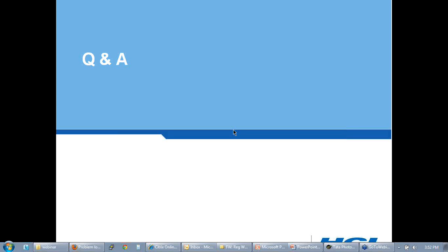So when you want to write any data again, it should be at its initial value, and only then can it be reprogrammed. This is one of the basic properties of the flash, and that's why we go for erase before write.